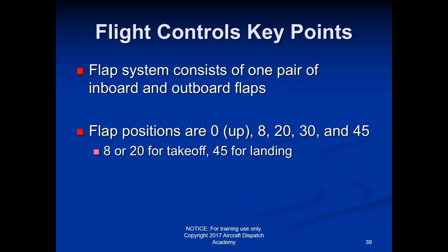I know we've talked a little bit about flaps, but just to recap, the flaps are on the back side of the wing. When they're extended, I'm sure everyone has seen them extend down to the varying degrees. Basically, all the flap is doing is changing the shape of the wing. If you think about the air going over the top of the wing and flowing off the back straight, well, if the flaps go down, then that air has to travel down further, and the air that goes underneath the wing is curving at the end and going underneath that flap. Basically, that whole process makes it so that the aircraft creates more lift. That's all it's doing. So when the flaps are up, the aircraft isn't creating as great of lift as when the flaps are down.